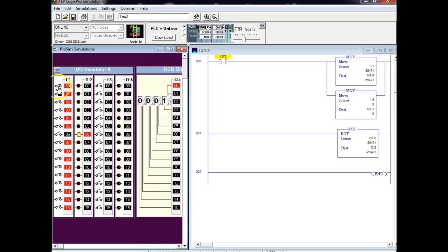What do you mean? This is an input. We're bringing in the whole input. So we're bringing in input module 1. And how many bits? I'm not specifying a slash up here. So I'm taking input module 1, not slash anything. So since I don't put a slash, we're designating that as the entire 16 bits.